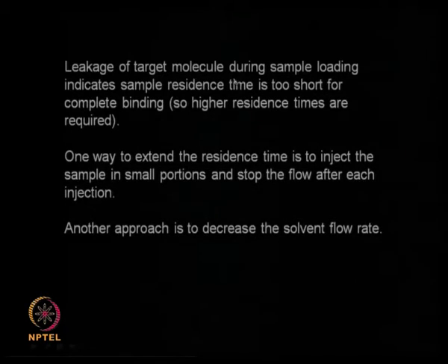Leakage of target molecule during sample loading indicates sample residence time is too short for complete binding, okay. So slowly the target molecule is coming out, that means you are not giving enough time for the ligand and the protein to interact. One way of addressing that is we inject a little bit, then stop the flow, then again inject and stop the flow, okay. So multiple small injections, that is one approach.